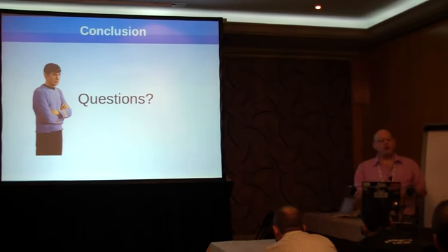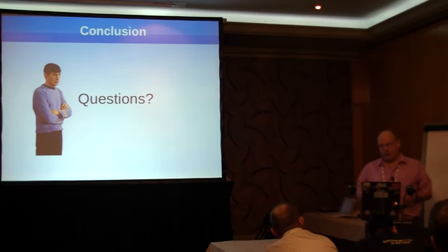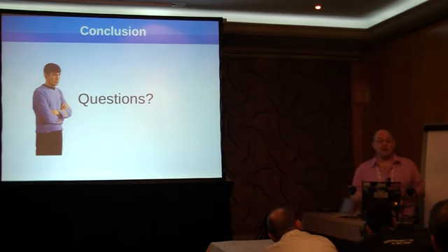The question is, I've referenced I2C for storing data, so what about SPI? In this particular context, there are a couple things. First of all, SPI tends to be a little bit more difficult to set up on a controller basis, whether it's in bootloader or something else. The second is it actually requires more wires, and when I'm debugging, I don't want to solder more wires. I want to keep it down as minimal as possible.